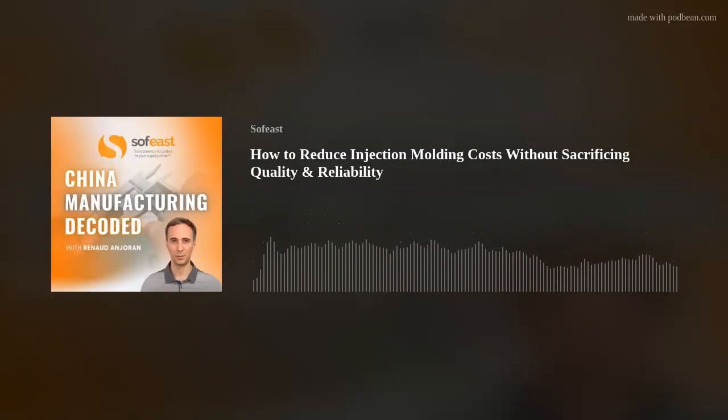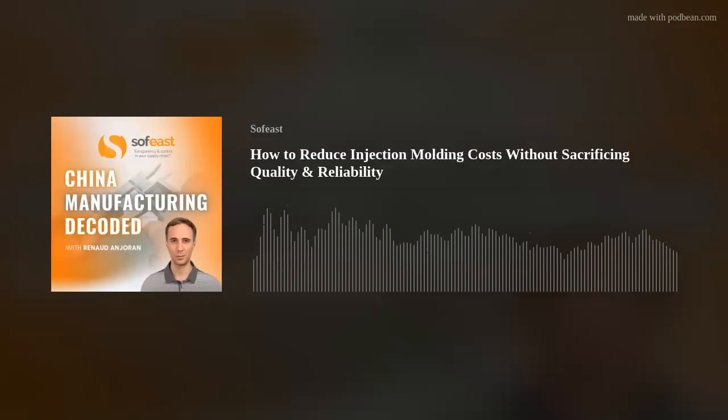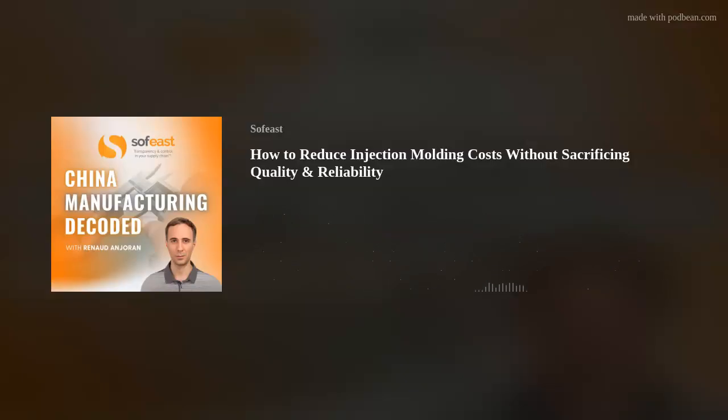If you ignore best practices, where your design goes around a corner and then you've got a rib and you haven't taken into consideration the ratios of the rib, and everything's uniform thickness, you're going to have problems. In other words, you're going to have sink marks and a very poor surface finish on the A surface, the outside surface that matters, because you haven't followed best practices.